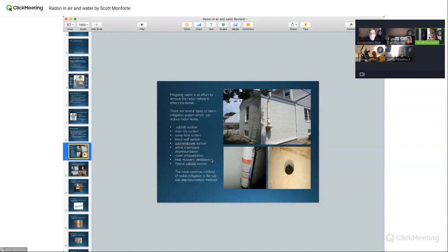So when you spray foam the attic, is it conditioned or unconditioned? Well, if there's no heat source, it's unconditioned. Technically, you're correct. No heat source, technically, you're right. But when you go up in an attic and it's 100 degrees out, it feels pretty comfortable, right? It's conditioned, yeah. It's technically part of the building envelope.